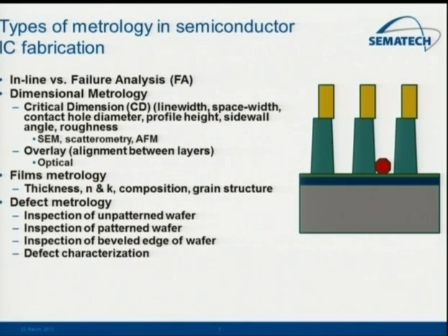I'll mention some of the techniques we use for that metrology. And another portion of this is overlay. When we're making semiconductor devices today, state-of-the-art devices may have as many as 50 different device levels. So part of it is how do they line up vertically. You print one pattern, you want the other pattern to line up with the previous one. The overlay between those patterns, and that's what we call it, overlay, is also very critical in terms of making sure that they line up. Because if this contact doesn't land on this line and it lands all the way off, of course, there'll be no electrical contact and that won't work. So you need to be able to measure the position of this layer versus the position of underlying layers.